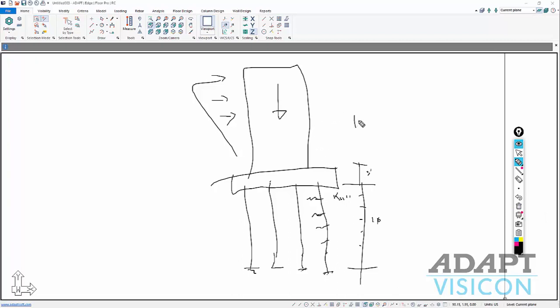I'm going to have 10 levels above grade. These will be 10 feet on center. And we're going to just model a fairly simple structure above the mat level. So we want to make sure we have 10 levels above. This is going to be our mat level, or cap level we'll call it, and then we're going to have 10 levels below. We're going to have the base of pile, and then pile 1, 2, 3, 4, 5 through 8, mat, and then above that, the superstructure.